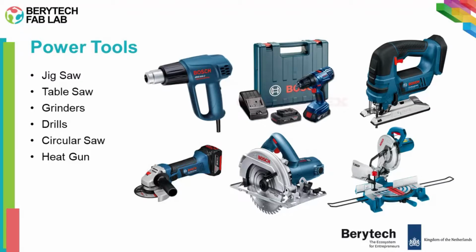We make the design, we digitally model the design on the computer. We then produce it either by using a CNC machine or a 3D printer. We make the shape, which you call the master. And then we build the mold using the vacuum forming machine on this shape that we want. We remove the shape and we can use the mold to pour in it whatever material we want.